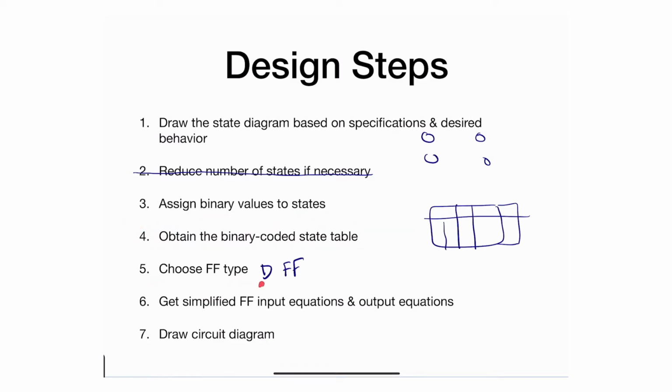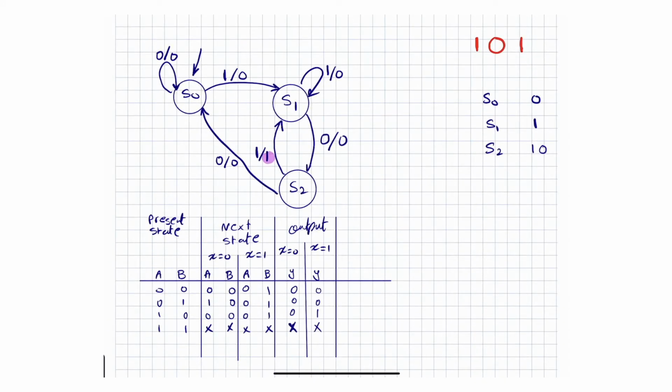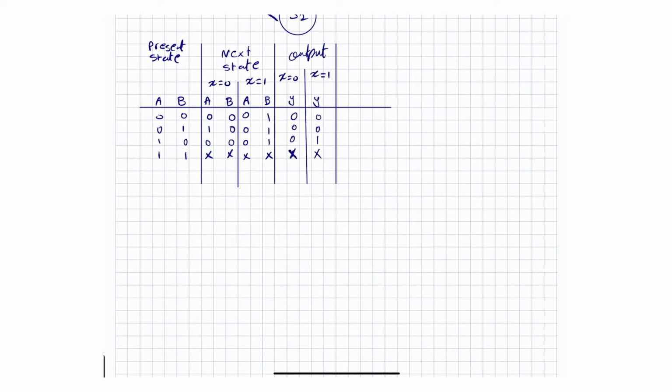If we're using the simplest flip-flop, all we have to do is come up with some sort of an input equation and output equation for these flip-flops. Really what I'm trying to say is, you're going to have to figure out what you need to put for these flip-flops A and B, and write these state equations and also the output. So I have a flip-flop A and a flip-flop B and only an input X, so I have 3 different variables. So all I have to do is come up with a Kmap that is a 3-variable Kmap.